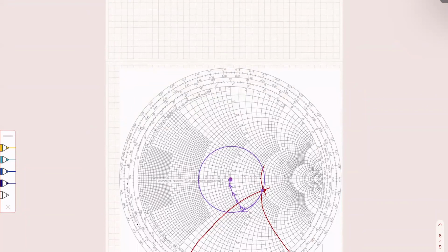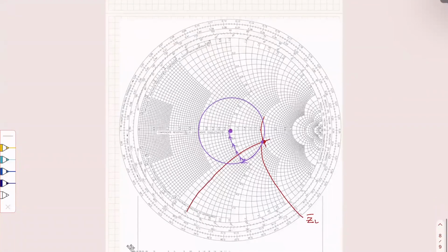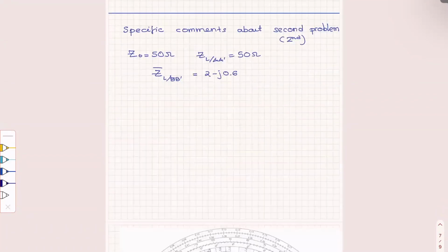However, when you go down to the other problems, you want to take the design of problem 2 and realize it in microstrip. After you do the design on the Smith chart, you will take the values, which are in wavelengths, and Z naught, and use the formulas in that section of the chapter to find the width of the microstrip and the length. And the wavelength, obviously. It says the frequency is 2 gigahertz. The last one is a continuation of problem 3.